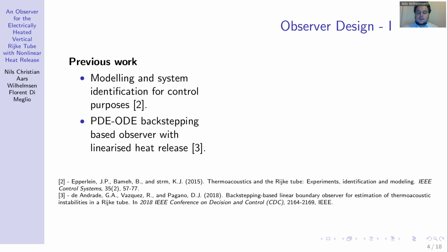An observer for the electrically heated vertical Rijke tube is derived in this reference. They base their design on the PDE-ODE model of the former reference and apply the backstepping method to design the observer. However, the heat release from the electrical heater, which is in reality nonlinear, is linearized in their design.